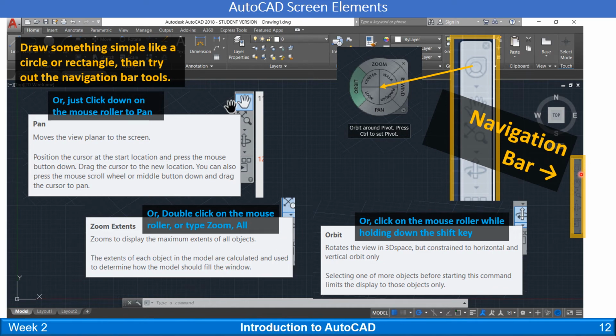So you can do that with the navigation bar, you can type it into the command line, or use that roller button on your mouse. It doesn't just roll, you can click it like a button. So if you double click it, it zooms all. Click it down and just hold it down, and that turns your cursor into a hand to pan. Or if you click on the mouse roller and hold it while you're also holding the shift key, that will let you open up the orbit command, and this will orbit around what you're doing.